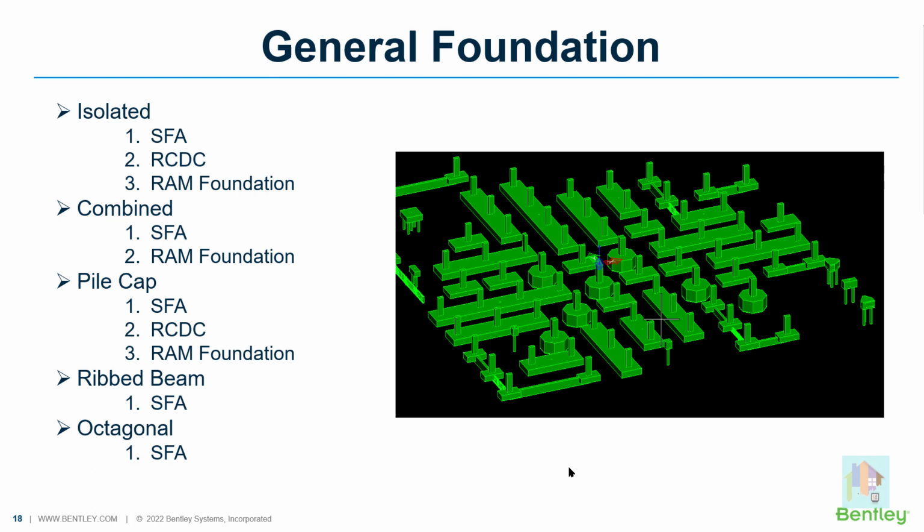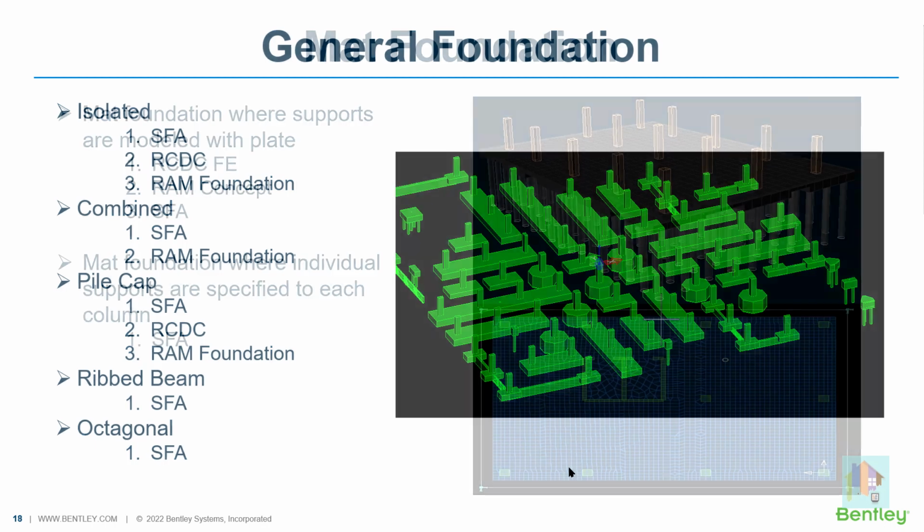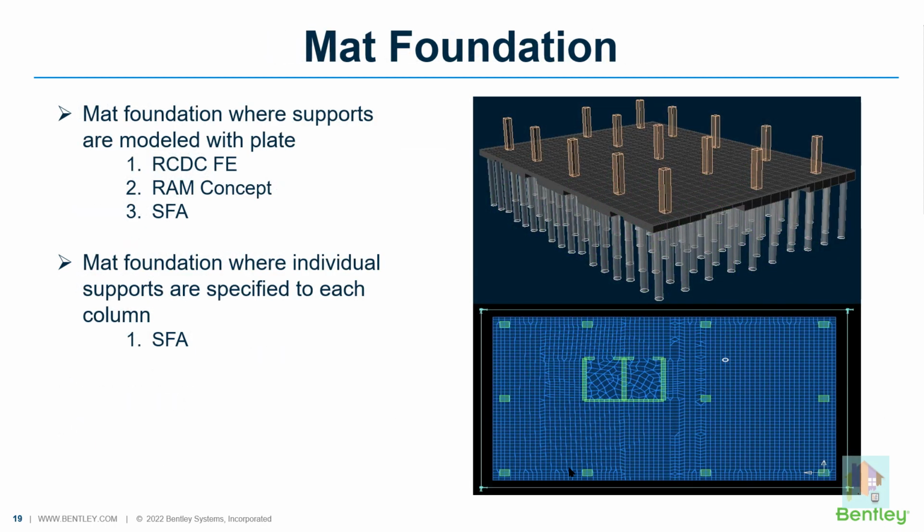But if you want to model your structure in STAAD.Pro, then the best choice would be using the RCDC or STAAD Foundation Advanced mode to design this type of foundation. And for mat foundation design, if we talk about any high-rise building structure, then obviously there will be mat foundation along with the pile cap. Means along with the piles. So if there are multiple basements, you need to go for mat foundation.